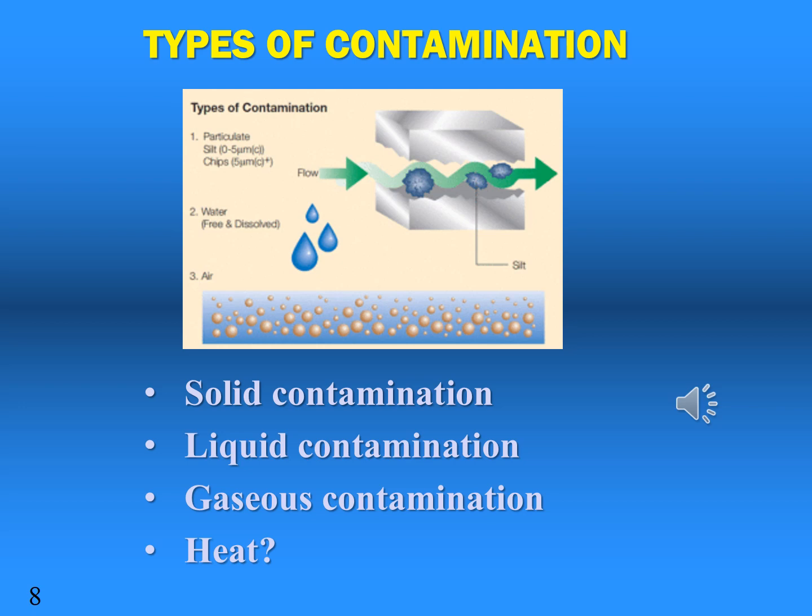These are the most common types of contaminants. Solid contaminants represent particles which do not dissolve and or have abrasive effect on metal surfaces. Liquid contamination may be water or chemical. Gaseous contamination is usually in the form of air in the oil.